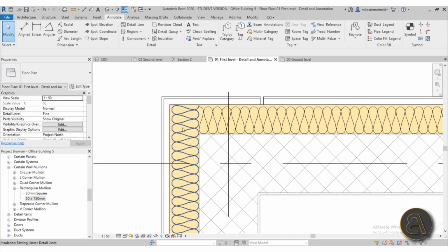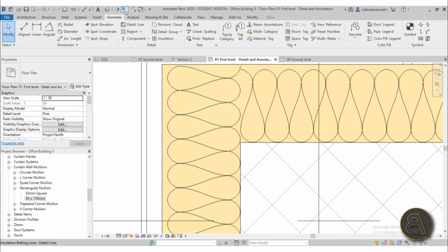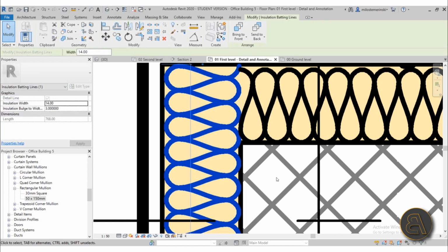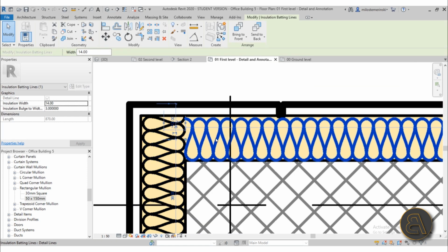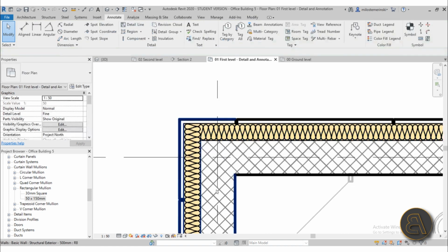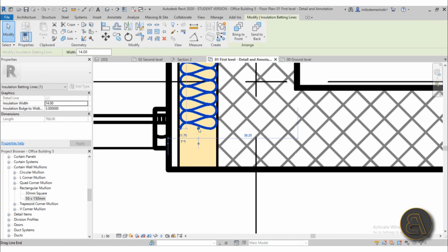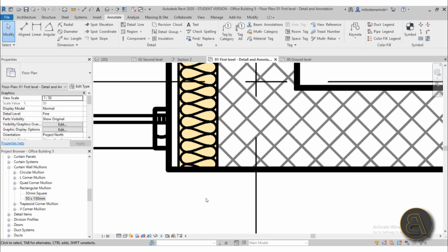Now the reason why I left that extra room over here is when I turn off thin lines, you're going to notice that these lines get a bit thicker, the exterior lines. So I like to select this, and then just by using the arrow keys, just center it just a little bit. Same thing here, just move it up just a little bit, and now it looks a lot better. Same thing here, select it and then use this grip point to extend it all the way to the outside.